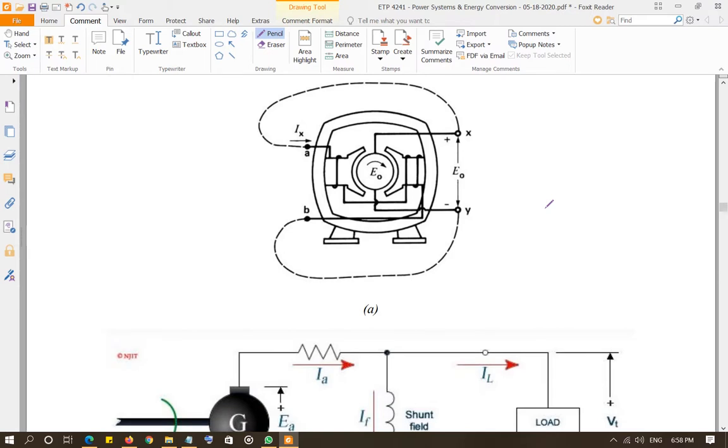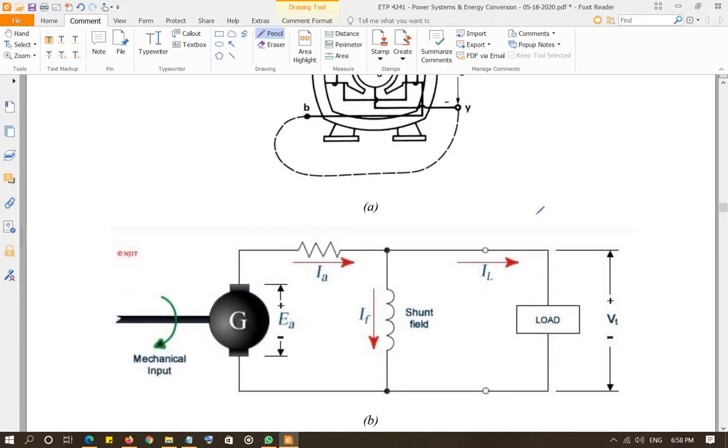So the same thing we are going to use to our advantage in the shunt generator. When you create a shunt generator, you energize the field coil, and then of course you remove the supply, so it de-energizes, but there is still some magnetism left in that electromagnet. So when you crank your armature, when you move the armature using a mechanical input or turbine, there is a little bit of weak flux in the shunt field that is linking with the armature.